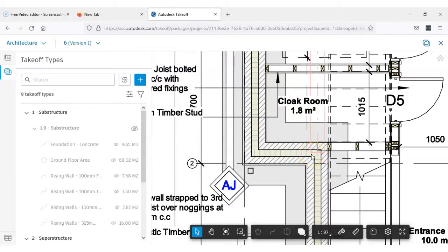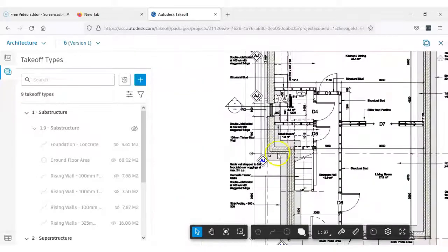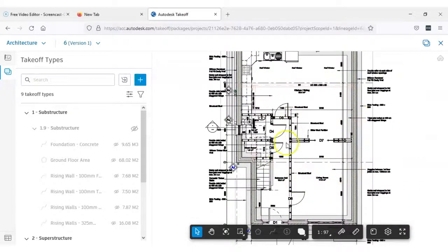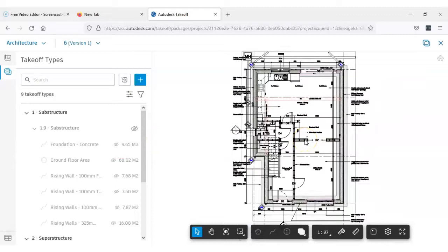is essentially in the substructure, and that is everything, including walls, the floor itself, the build-up of that floor, hardcore, blinding, insulation, the concrete itself, and excavation, trenches, everything that goes with creating that substructure, creating that foundation and ground floor. External walls then builds up from the rising walls that you've already measured, and it goes right up, obviously, to the other side of the roof.